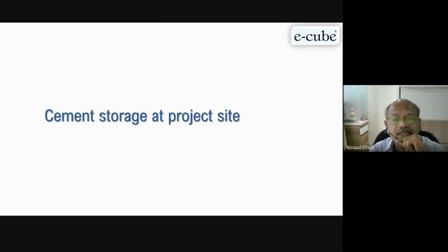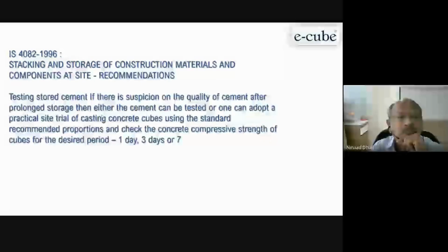So it is very essential to understand, when you go to the site, how they store the cement. So I'll just have a few slides for that and then we'll close today's lecture. There is an IS code for this. You can just note down this number: IS 4082, stacking and storage of construction material and components at site, recommendations are there.